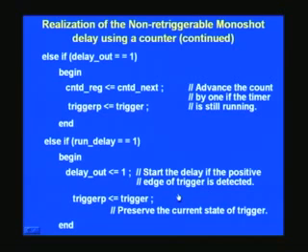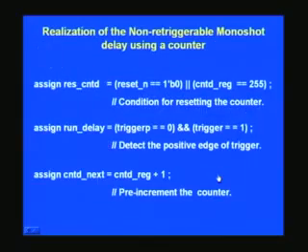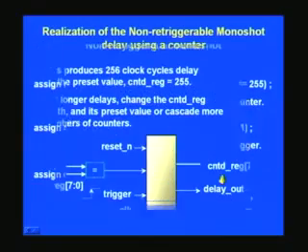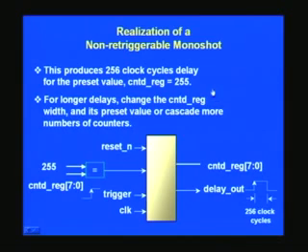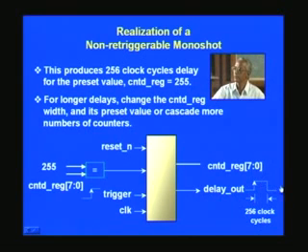And one more thing I wish to say is, we have seen this delay out as 256 clock cycles. So that's what we have by equating it with 255. And why 256, we'll see when we see the simulation. We'll have an explanation for the 1 extra cycle.